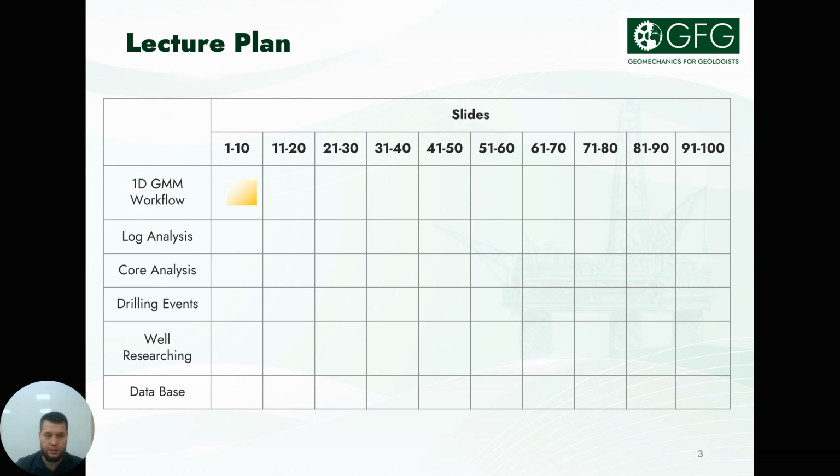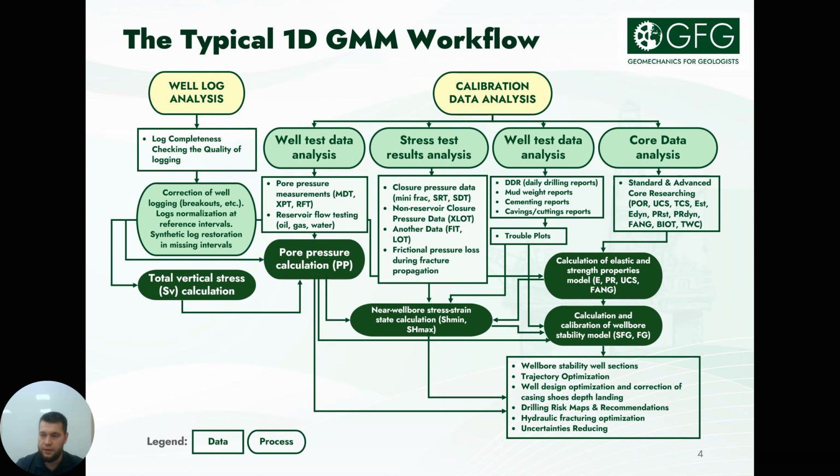First topic is 1D geomechanical workflow. So the slide presents a typical workflow for building a 1D geomechanical model. This workflow includes the stage of data analysis as well as the necessary calculation of mechanical properties and stresses.